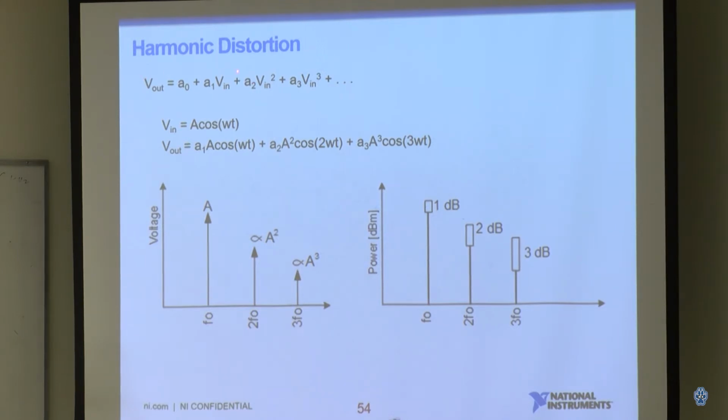And this other topic called harmonic distortion. Remember, the signal is a cosine or sinusoid signal, right? Let's say your input signal is perfect, but any analog device is not linear. In the real world, they have multiple terms. So when you have multiple terms dealing with your input signal, your output signal will eventually have multiple terms also. So this is the concept of harmonic distortion.